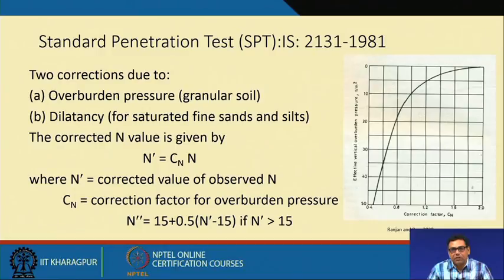As I showed you in the volume change versus strain or displacement curve, for dense sand the volume increases due to shearing. So if the volume increases, the pore water pressure will decrease.